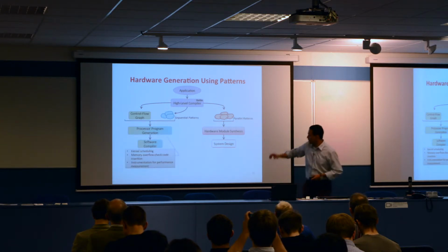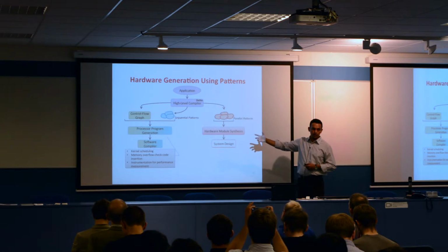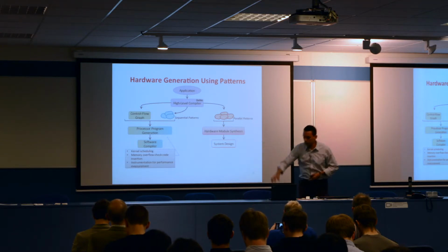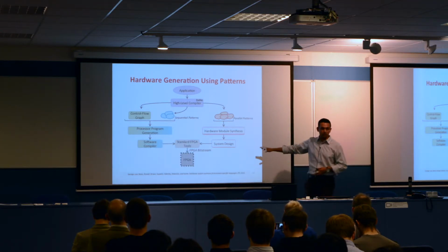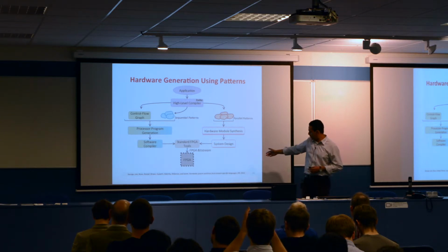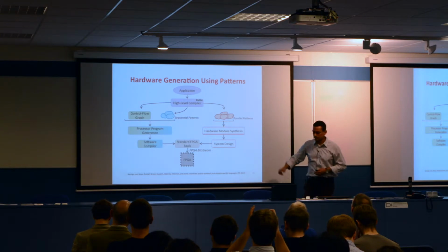Now, for the rest of the code, which is the sequential pattern and the control flow graph, we synthesize a software program which schedules the different patterns correctly and executes the entire application. Putting these two things together within the standard FPGA tool flow, we can generate complete bit streams. That's what we have been building. This is work which we presented at FPL 2014, last year.